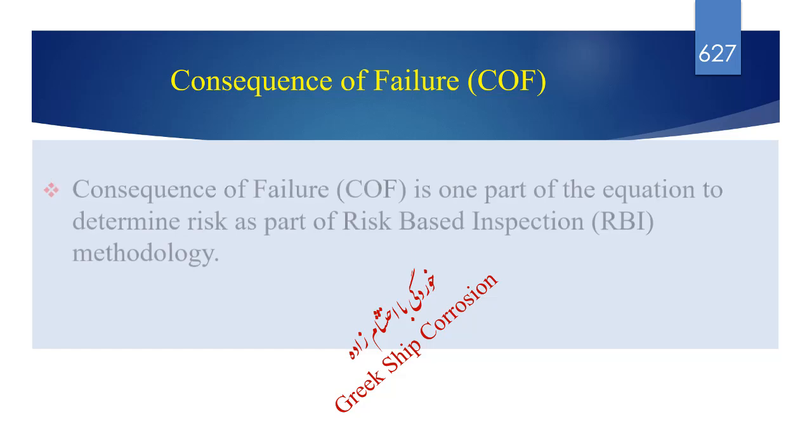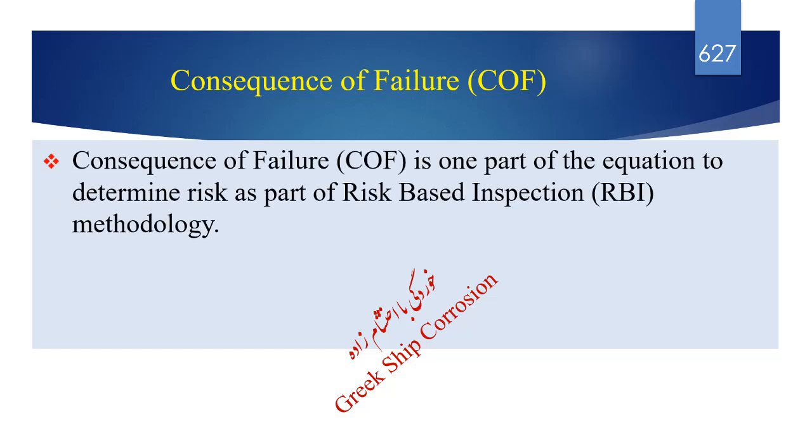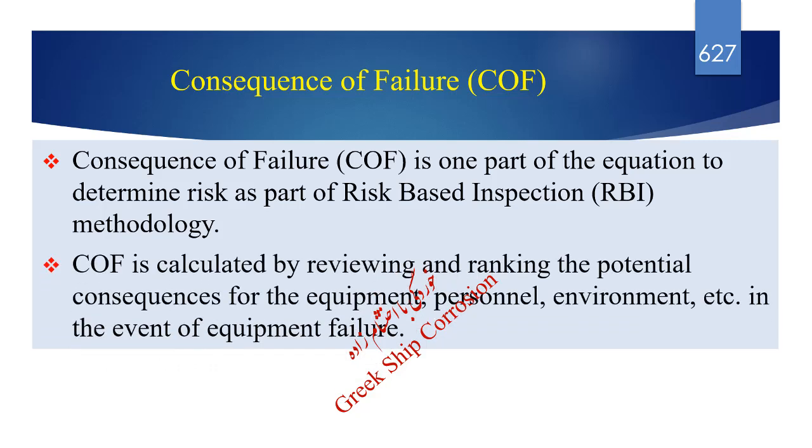Consequence of failure. Consequence of failure, or COF, is one part of the equation to determine risk as part of risk-based inspection methodology. COF is calculated by reviewing and ranking the potential consequences to the equipment, personnel, environment, etc. in the event of equipment failure.